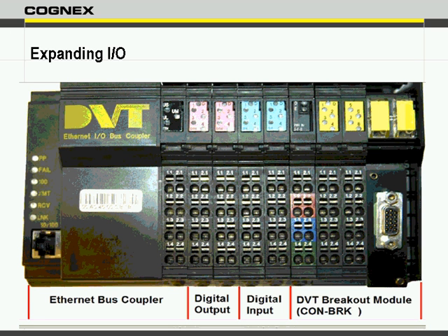There's a white tag on the very front of it, which will give you its MAC address, and you can assign an IP address to it and a mask, and then enable that, and that will connect you through the Ethernet to your camera, which then will become functional for you.